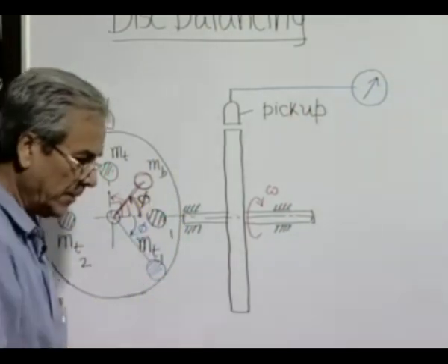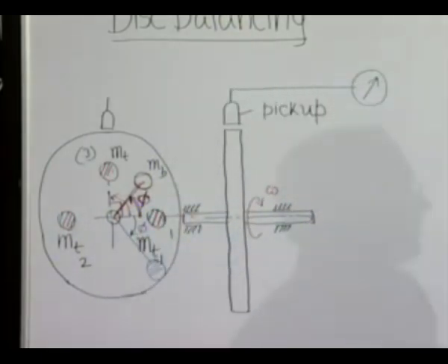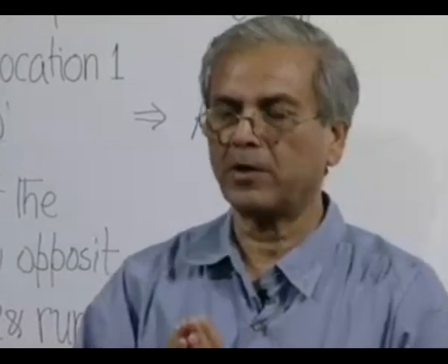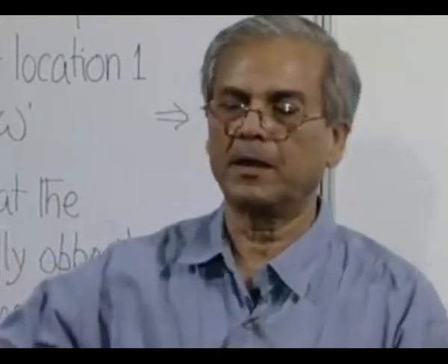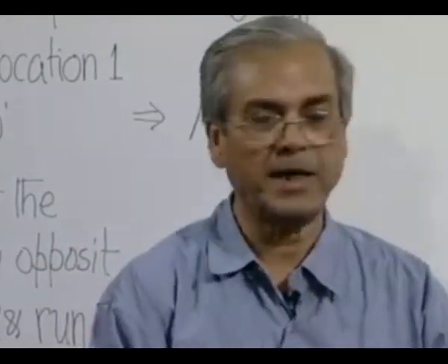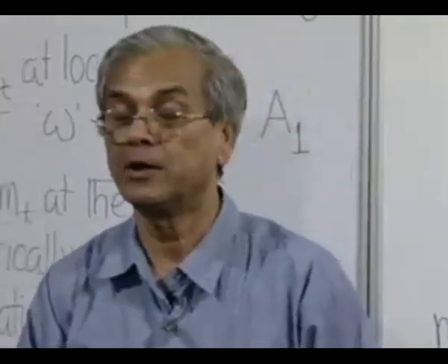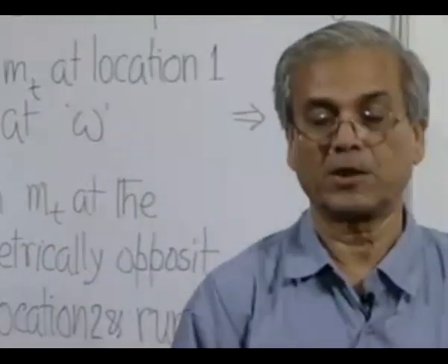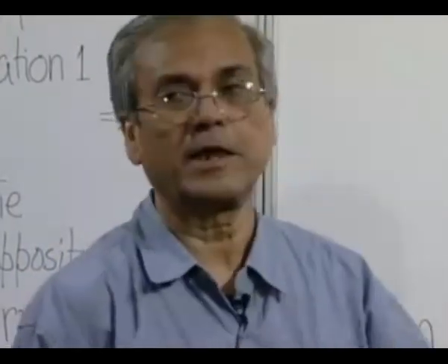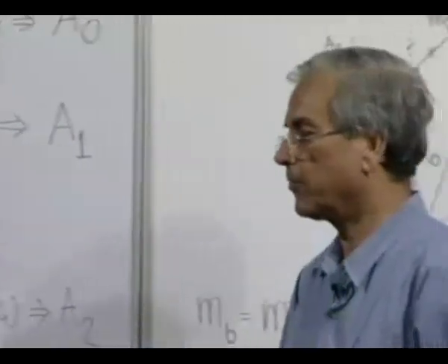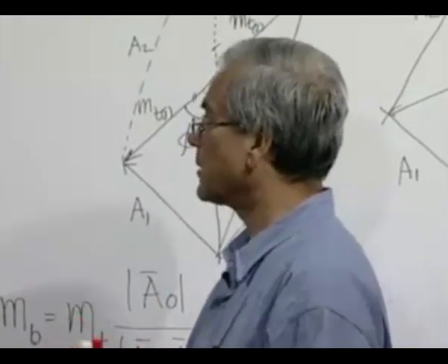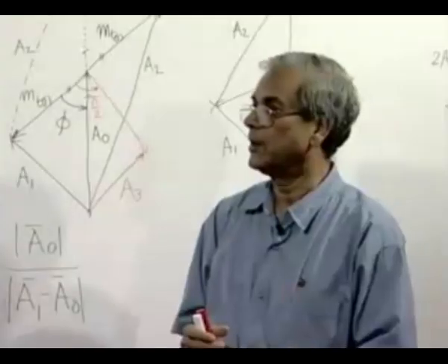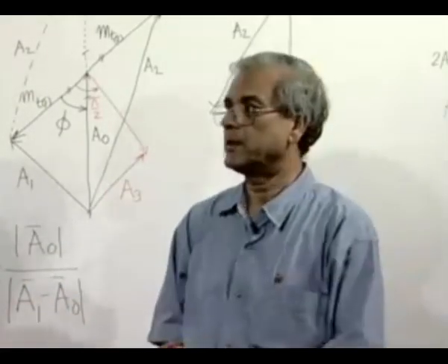So, this is the way we handle the field balancing problems of disk-like objects. Disk-like object means most of the matter is considered to be confined to a plane which is perpendicular to the axis of rotation. Now, I think in the next session we will extend this technique of disk-like objects for finding out the balancing mass required by some experiments in the field in its own position for rotors. That is a very major problem.